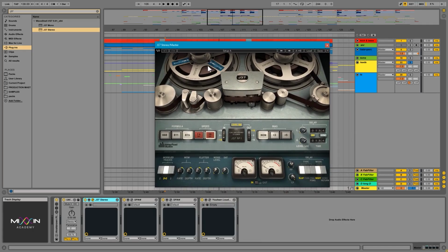Now, a characteristic of a tape was that once you overdrive the sound into a tape, so you try to record too hot with the levels too high on the input into the tape machine, well, one of the artifacts was produced because the tape in its physical form, when you try to overdrive it, you're just trying to magnetize more particles than there actually are on a tape at a certain point. So that kind of distortion sounded much different than nonlinear. That kind of distortion also introduced some compression, and really had a sound of its own.